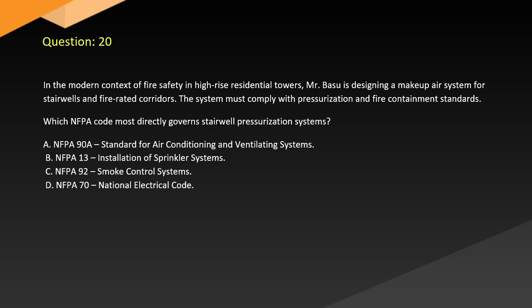Question 20. In the modern context of fire safety in high-rise residential towers, Mr. Istabosu is designing a make-up air system for stairwells and fire-rated corridors. The system must comply with pressurization and fire containment standards. Which NFPA code most directly governs stairwell pressurization systems? A. NFPA 90A, standard for air conditioning and ventilating systems. B. NFPA 13, installation of sprinkler systems. C. NFPA 92, smoke control systems. D. NFPA 70, National Electrical Code.